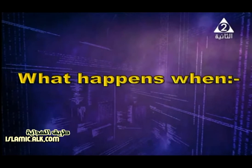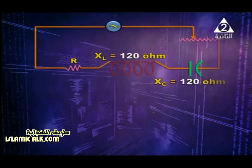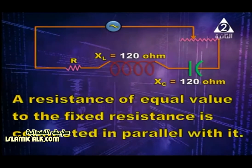What happens when a resistance of equal value to the fixed resistor is connected in parallel with it? Your attention, please. Here we've got a circuit in a state of resonance. Why is it in a state of resonance? Simply because XL is equal to XC. Inductive reactance is equal to 120 ohm. Capacitive reactance is the same, 120 ohm.